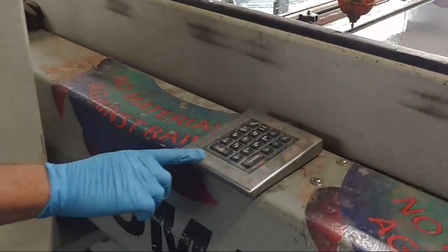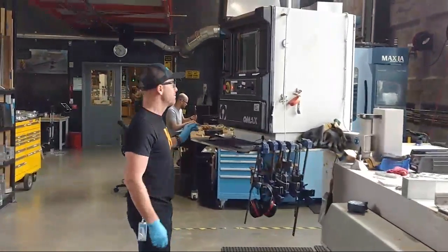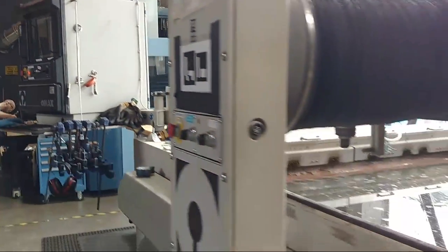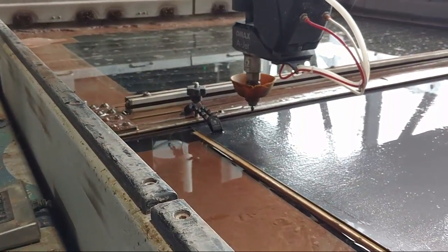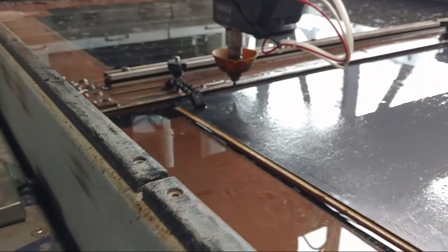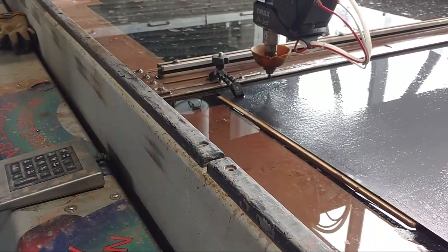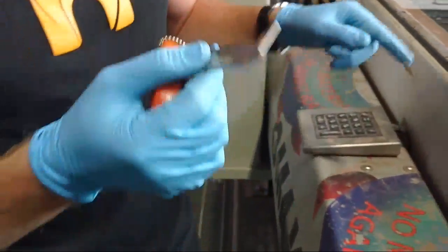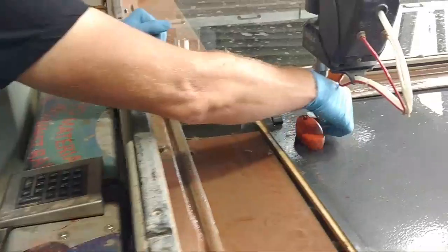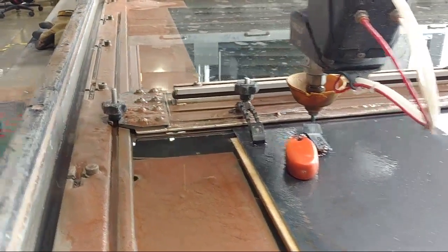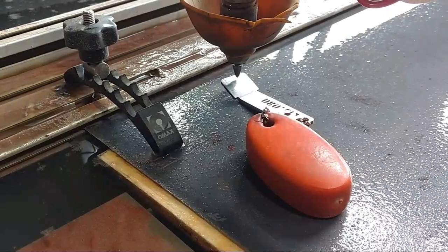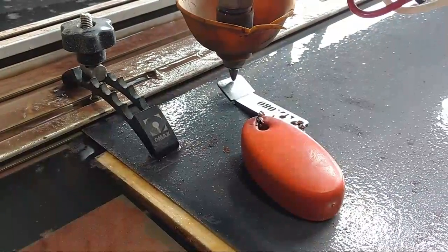Next thing we need to do is bring the Z to where we want it. So that's kind of far. I can control it from here, but it's a very slow feed rate. So at the main control, I'm going to bring it close, jog it down to Z. Now I'm going to come over here. We've got this 80 thou. It's like a feeler gauge, so you get the tip close to the material with this. I'm gonna jog it down nice and slow. It is moving very slowly. So we'll see that thing make contact.